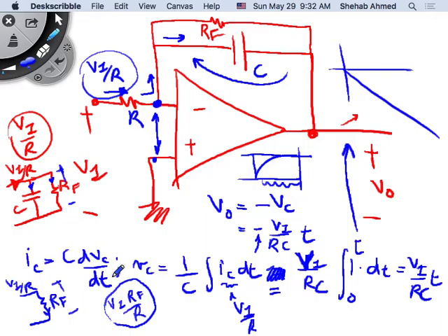Right? But now go back to the general case. The pulse that I'm putting in now is 1 millisecond only. So my job is to say, after 1 millisecond, what's happening? In the case without a resistor, after 1 millisecond, the voltage is brought to 0. So what happens to the output? Without a resistor, after 1 millisecond, I bring the voltage to 0, so the output voltage will be back to 0. This is the case without this resistor.